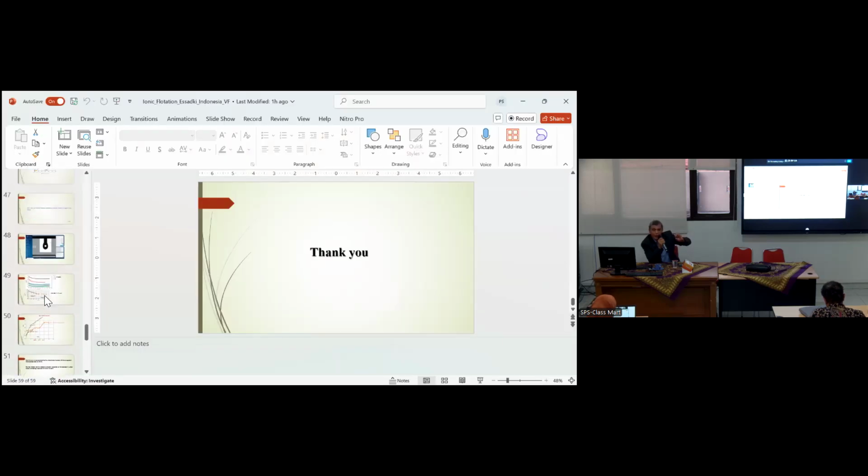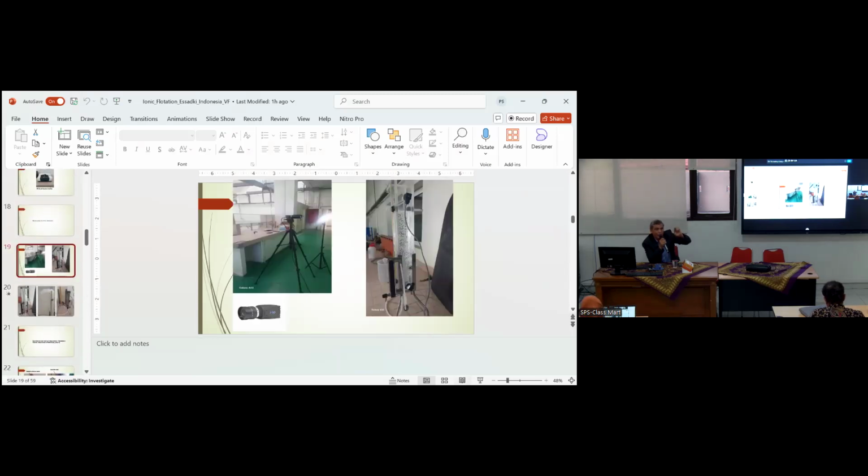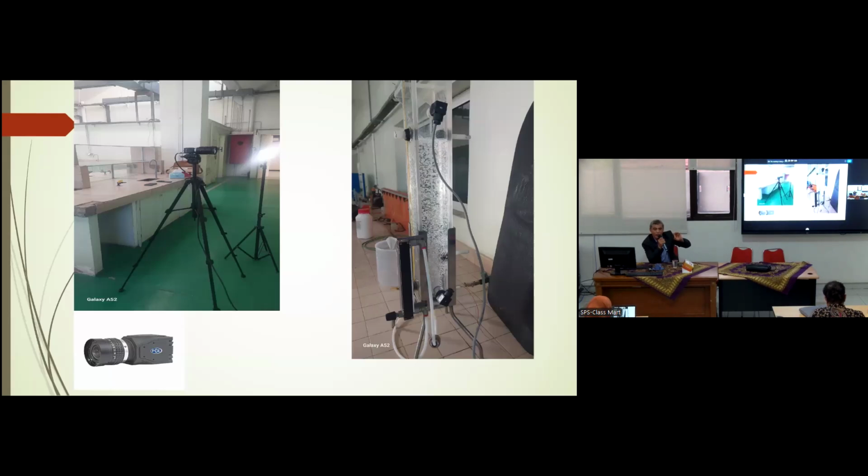For this, we have used a rapid camera, and we can record with the camera and see the velocity. We can measure the velocity of the bubble. But the diameter is not easy to measure. We have to analyze the image with special software to have an idea, but it's not easy even with software, because with a weak flow rate it's possible, but with a great flow rate it's very hard. We have to use a specialist for image processing.